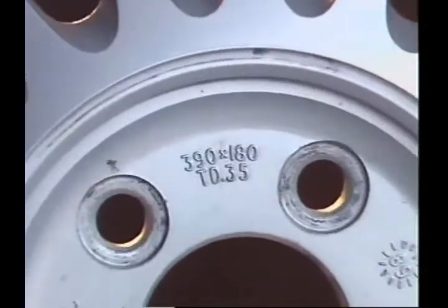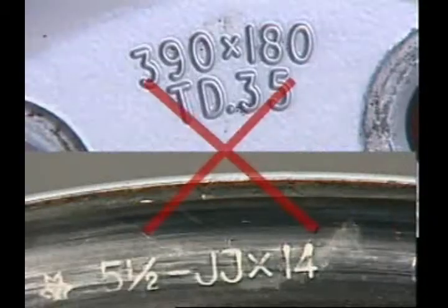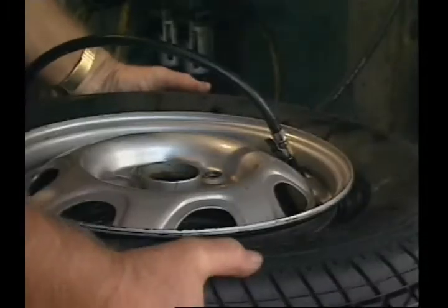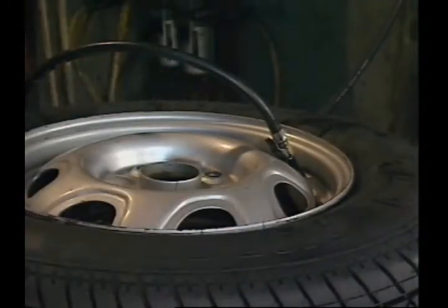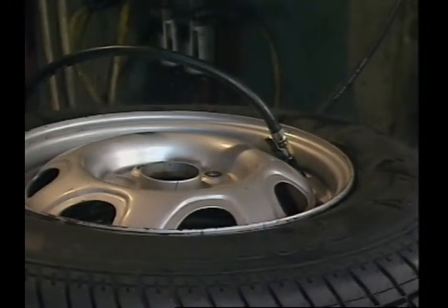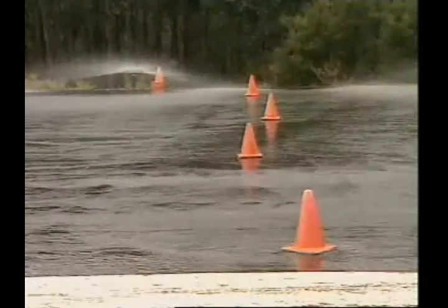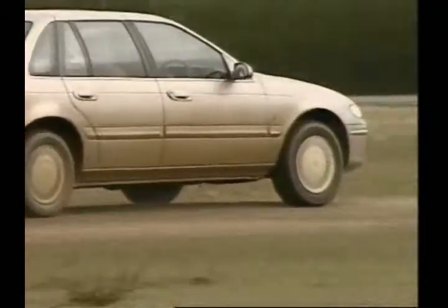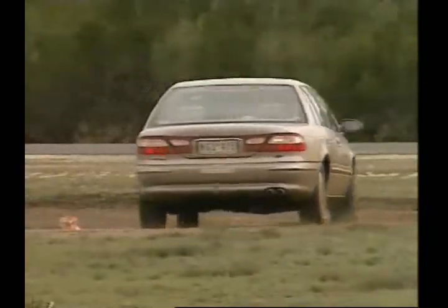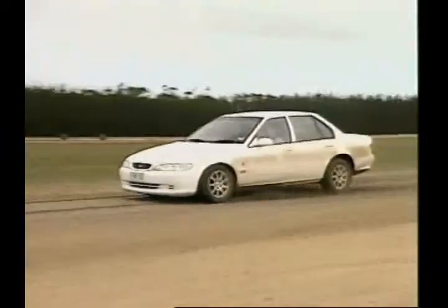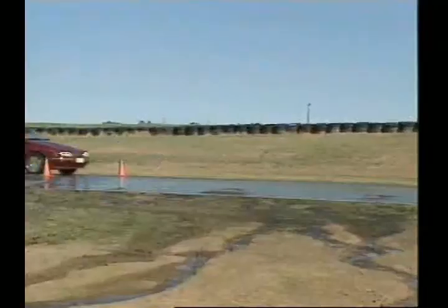The rim width and diameter can also be stated in millimeters. Metric rims are not interchangeable with imperial rims. The tyre must be an exact fit on the rim to fulfill a number of functions. It ensures that the narrow contact area between the beads of the tyre and the rim will seal the air in a tubeless tyre. It transfers all the forces between the tyre and the wheel without slipping or chafing. It ensures the friction between the tyre and the rim prevents the tyre turning on the rim.